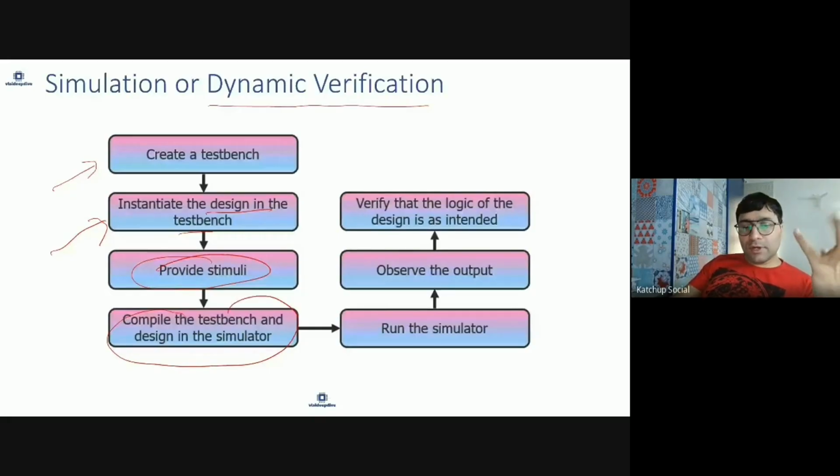There are a lot of simulators, as each big company has one. Synopsys has VCS, Cadence has NCSIM, Mentor has Questa. There are also open-source simulators like Icarus Verilog, and those can read in your RTL and test bench and verify the logic is working as required.